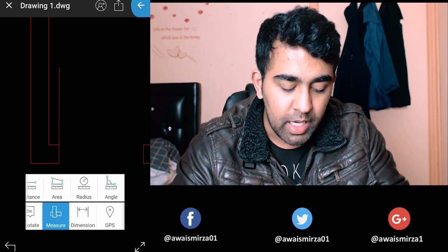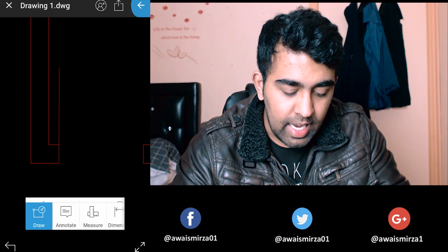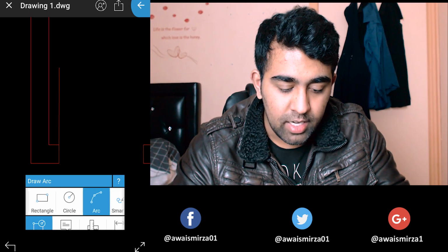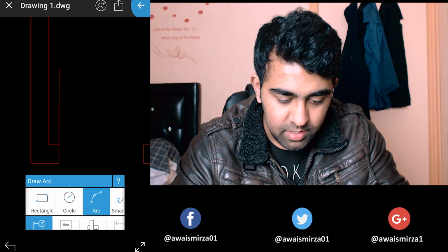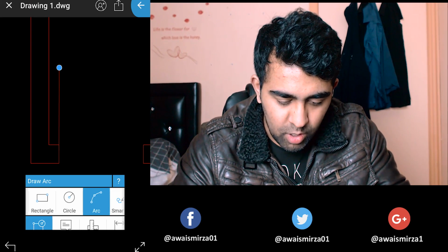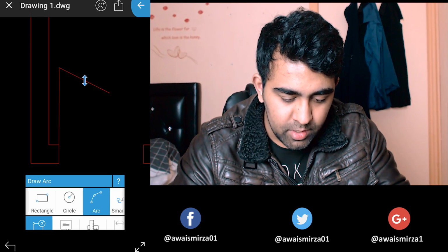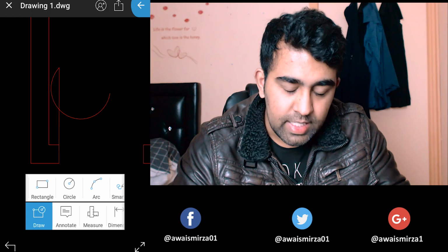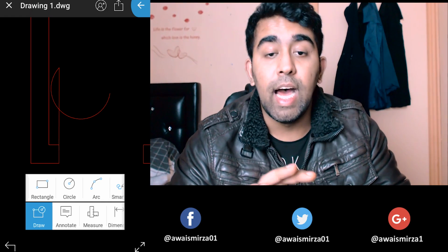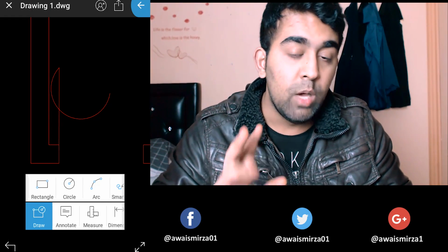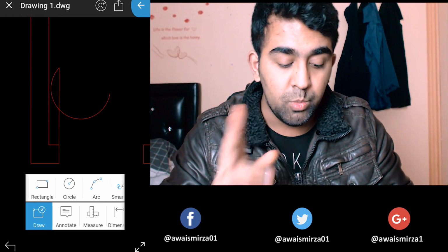I'm gonna go to my draw panel again and then select the arc tool. Alright, so I'm going to try snapping on the top of this line. Done. And I'm gonna tap here. Okay, and then I'm going to snap here. Alright, well, didn't work because that's a 3-point arc. If you know about AutoCAD, we got 3-point arc, we got 2-point arc.